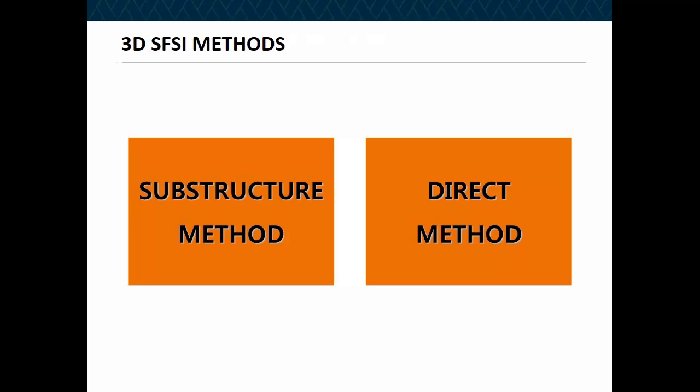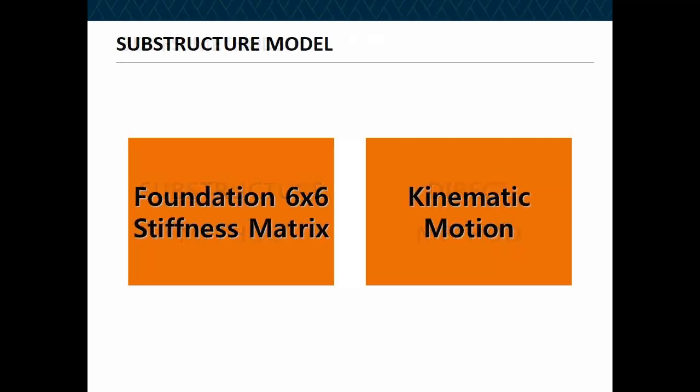We put everything as is in the model. Now, the reason we go for the substructure model is because many computer programs don't have the capability to run as fast, therefore we use substructure. However, nowadays, if the computer solution is fast, you had better use a direct method and model the foundation and the superstructure as one model, which I have done with Midas.